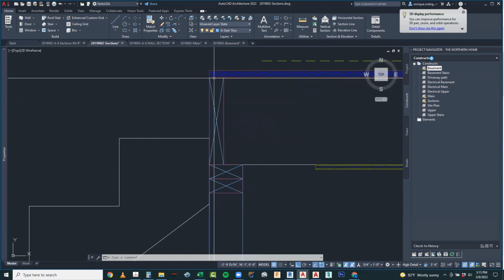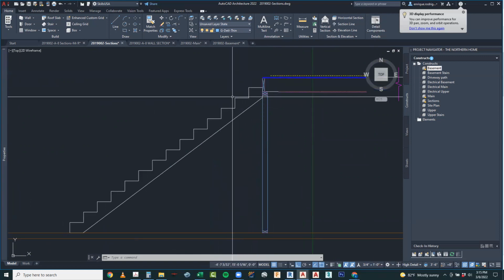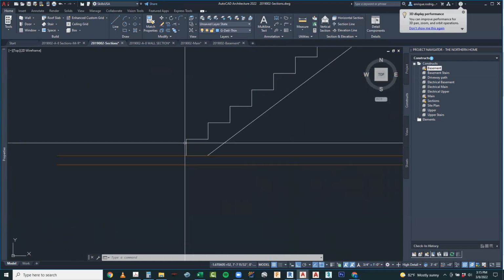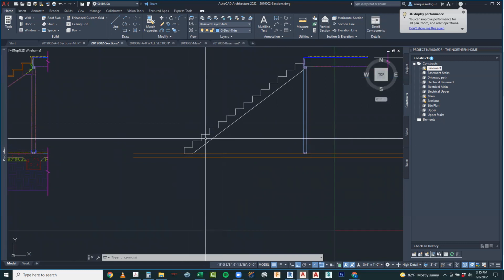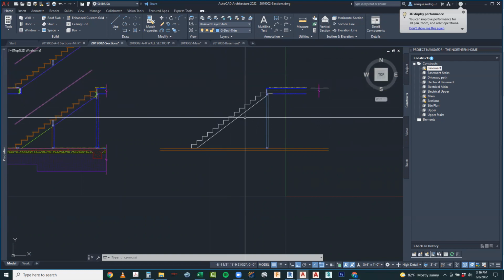So this plywood is 3/4 inch thick. All my treads are going to be 3/4 inch thick, and my risers are going to be 1/2 inch thick, coming up like that. What is important is that each step remain almost identical. You do not want a variation. That causes tripping, because people's brains work in a certain way: they get used to expecting to put their foot down at a certain point, or to have a little extra room. And if they run into something that's different, it becomes a hazard. And you definitely don't want to be tumbling down the stairs.